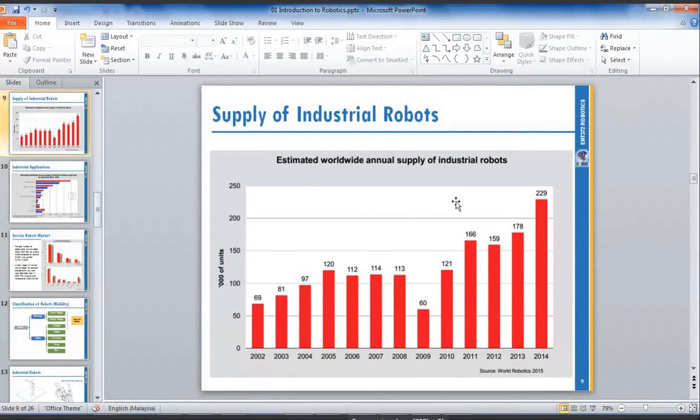When we do production, one frame contains about 20 or 30 LEDs. After they complete the process, they cut it to be singulated. Before they cut, before the product is complete, the LED diodes are fabricated on the frame.